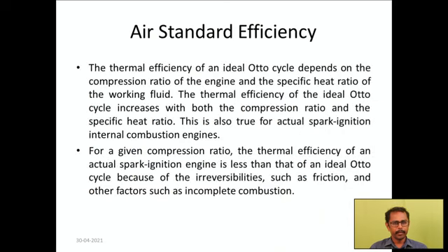Now the thermal efficiency of the Otto cycle depends on the compression ratio of the engine and the specific heat ratio of the working fluid. So the thermal efficiency of the ideal Otto cycle increases with both compression ratio and specific heat ratio. This is also true for actual spark ignition internal combustion engines.